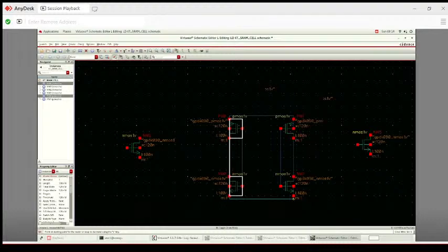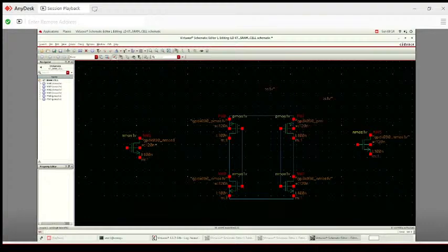Let's move forward. So here, yeah, a connection is missing. So now let's complete it. Okay, so now it's completed. Yeah, both sources of NMOS were connected for common ground connectivity. So here we have completed our inverters. As we can see, inverter 1 and inverter 2 are completed for a bistable latch design. It's still not a bistable latch because the input of the first inverter is not connected to the output of the second inverter, and the input of the second inverter is not connected to the output of the first inverter.